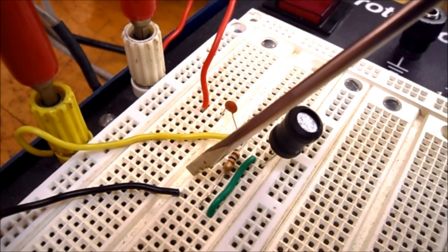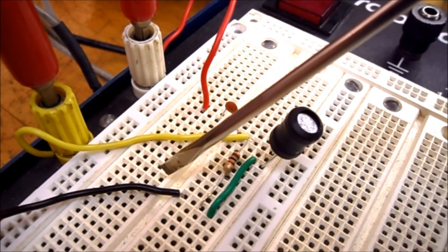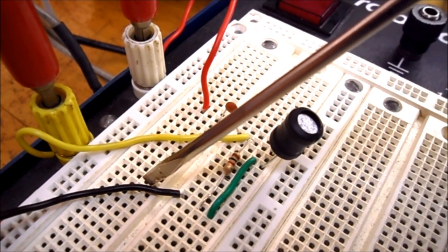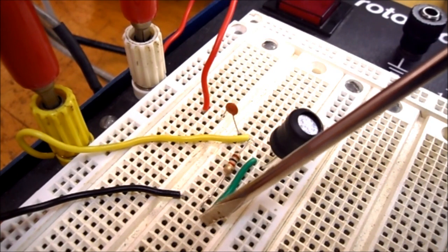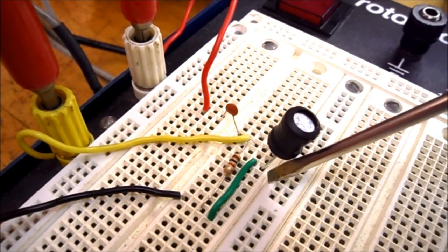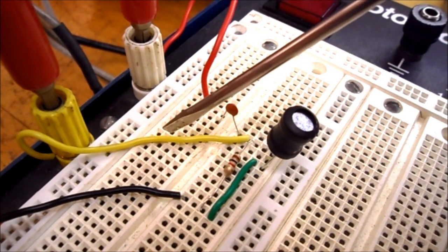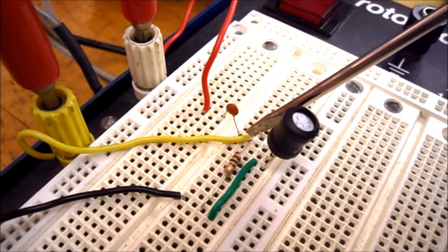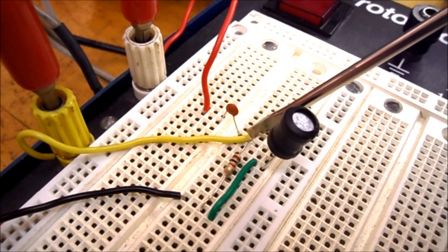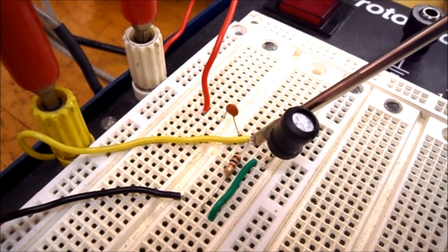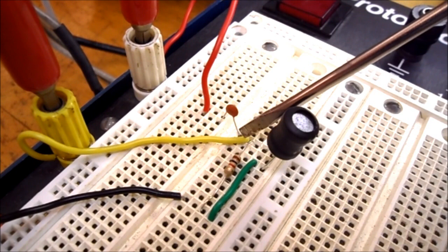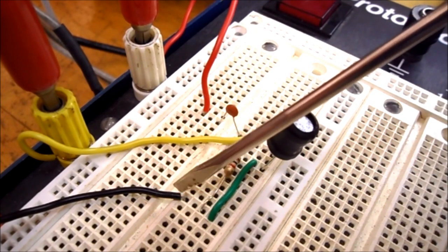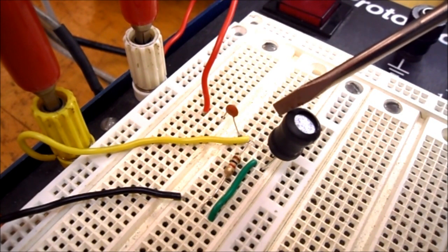So back here on my circuit, I've removed that 10 ohm sensing resistor and moved my common wire over so it's making contact with the bottom of the 1K and the green wire that goes to the bottom of my inductor. My sensing line, which goes to channel 2 of the oscilloscope, is now placed at the top of the 1K ohm resistor where it meets the inductor and the capacitor. So now I'm looking at the voltage across the resistor and inductor in parallel.